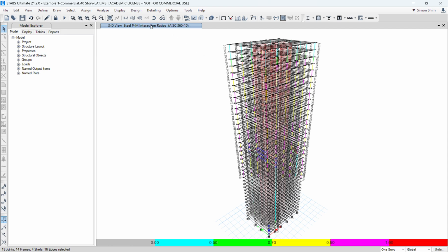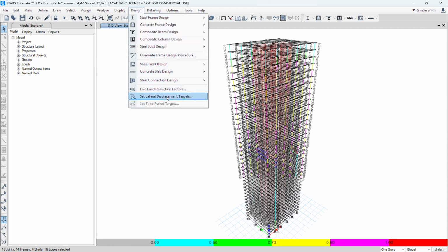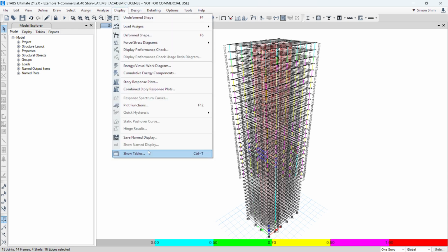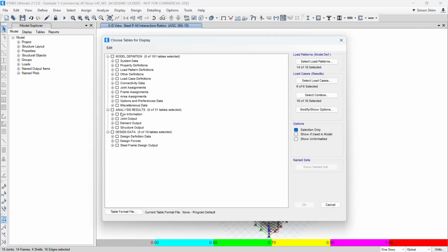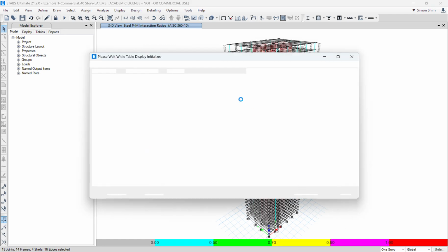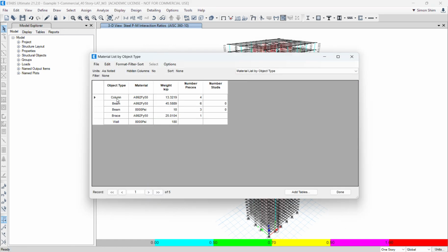And what I'm gonna show you is again the material tonnage. Assume that all the tower member sizes are complete. You need to pull out just the material takeoff here. You could sum them all up, the total column.